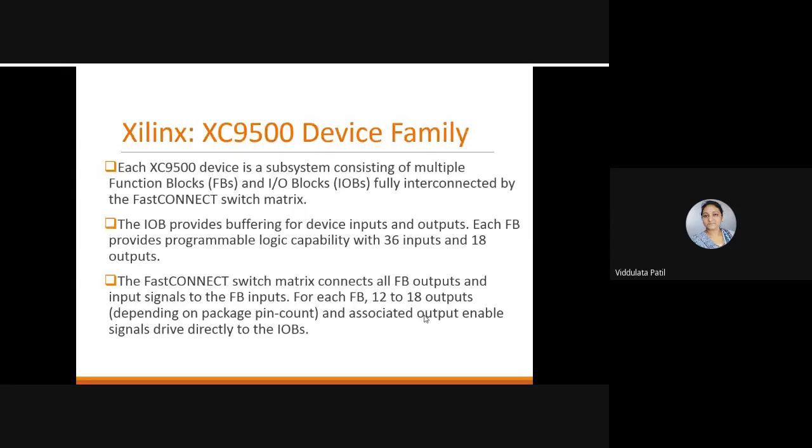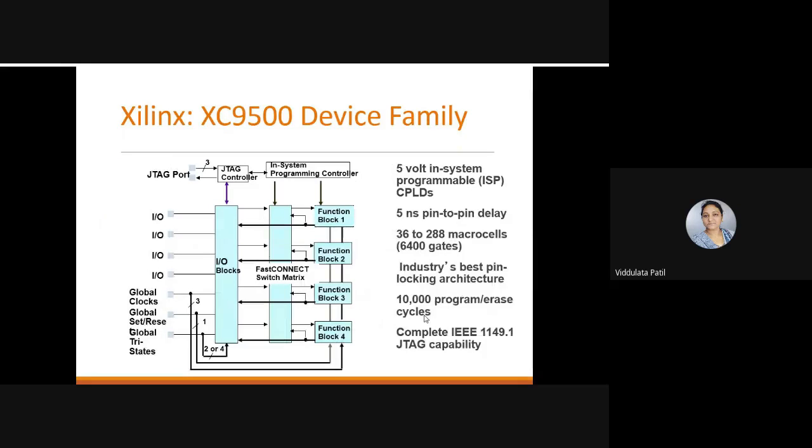So each functional block has 12 to 18 outputs associated with output enable signals, and these directly drive the IO blocks. Okay. So this is the actual architecture of the XC9500 device family. Here you can see the IO blocks that are present.